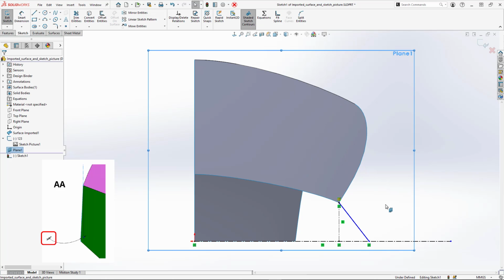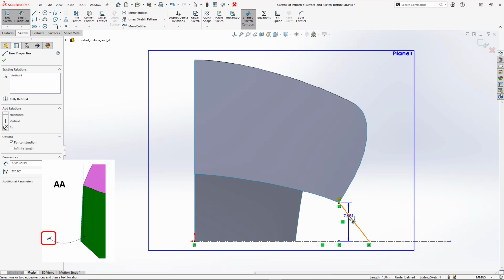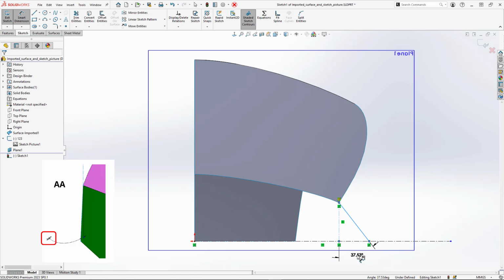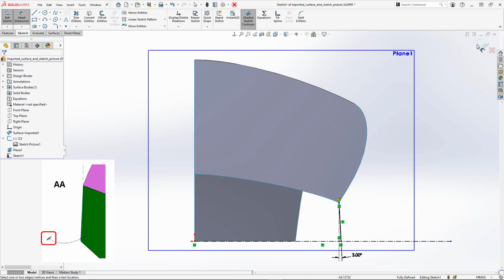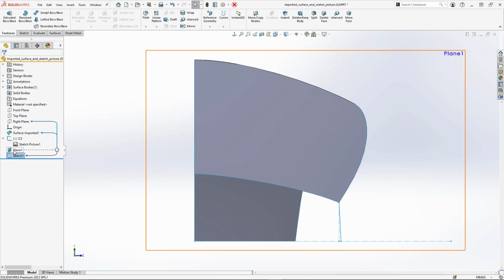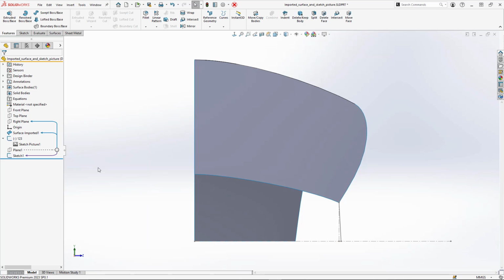And so that's what I'm doing here, I'm using a make pierce sketch relation. The make pierce is between the endpoint of a line and a 3D curve, which is why it ends up sweeping along a three-dimensional curve so well. Once I've added that sketch relation, I still need to add in my dimension. And I will add that 3 degrees. So the profile of my swept surface is actually completed.